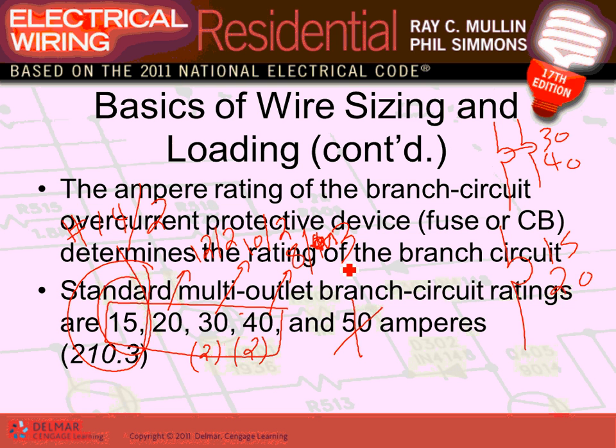Any comments, guys? Any questions? This one here will be for range. This one will be AC, typically. And all these here will be receptacles and lights. Done. You have just circuited the whole building. Any comments, any questions? So when we start, Karen, laying out the receptacles and grouping them, we're going to be using these concepts of these circuits.